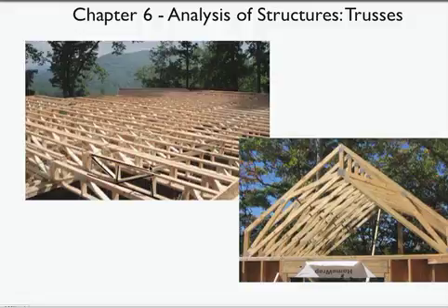So these are floor joists, and this is a ceiling or a roof joist. So this is designed to support a roof, so the roof would lie right up here. And again, same situation. You've got a bunch of straight pieces connected together to form a larger structure, which you will find in mechanics of materials would be stiffer and more resistant to bending than if it was a whole solid piece, except you use a lot less material.